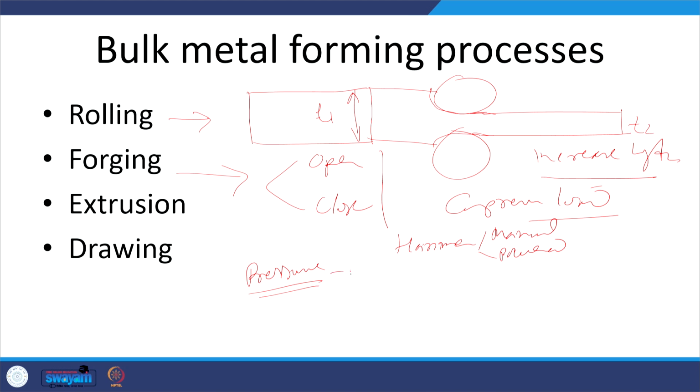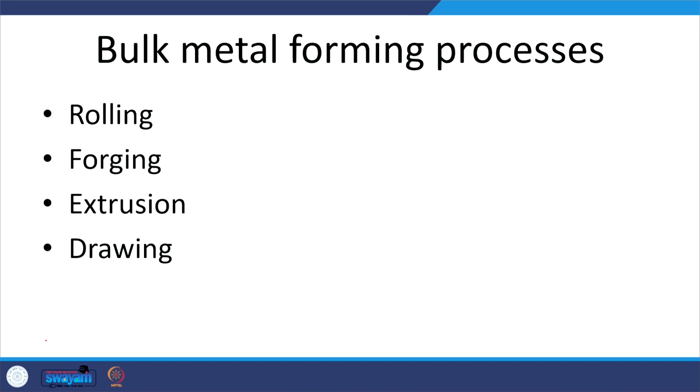So, with the help of a suitable press, this kind of approach is used for controlled plastic deformation of the material. In that case what we do, we take one die and the raw material is like this, and then the load is applied from the top, okay. So, the material will be filling the cavity and realizing the desired shape.